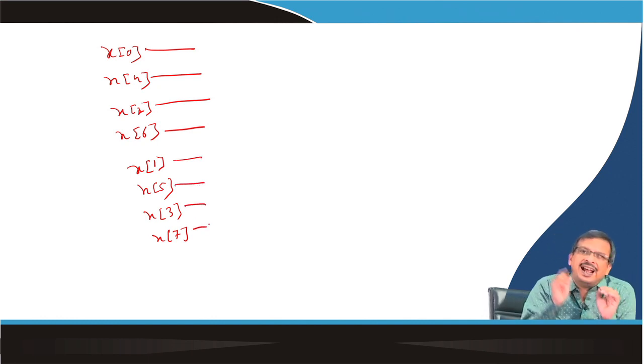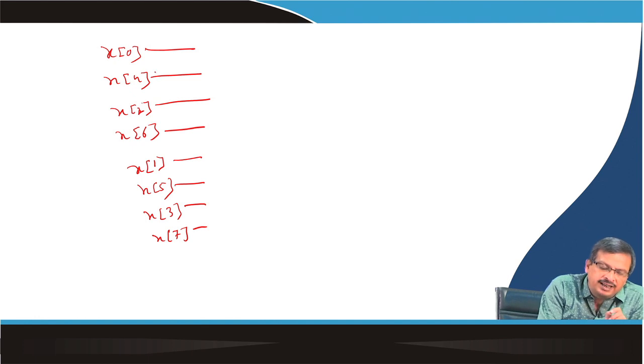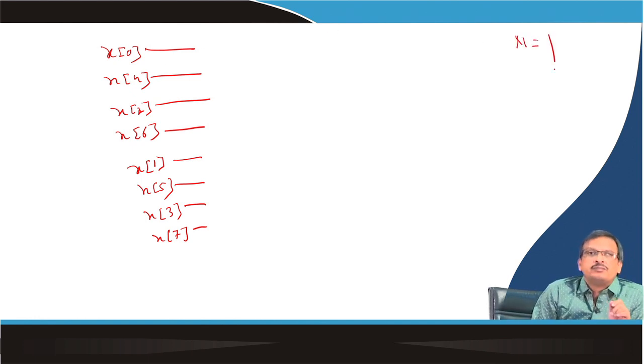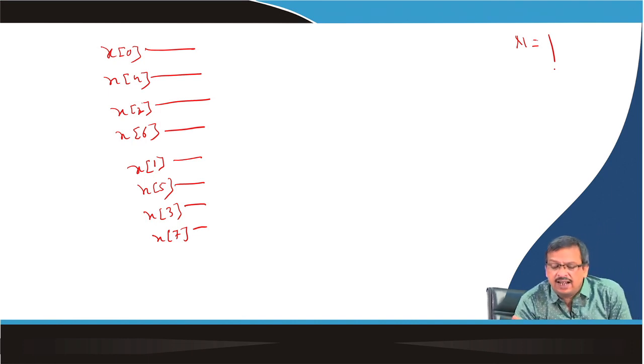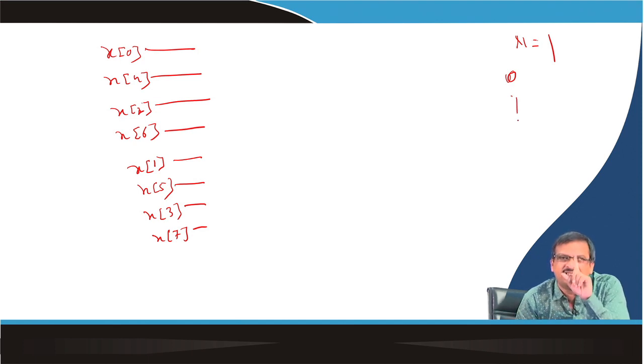Now, if you see, at the final stage the length of the DFT is n equal to 1. So, the length of the DFT is 1, so the even sequence length is 1 and the odd sequence length is also 1, a single-length sequence.